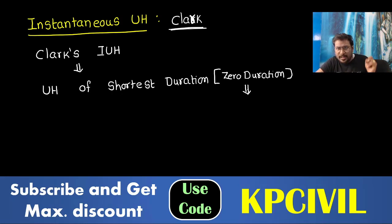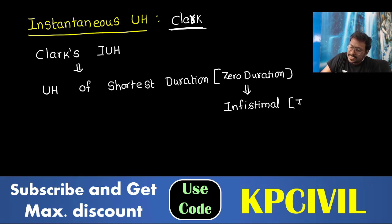I have taken only one value of discharge, starting at 0, ending at 0. What is the time gap? Exactly this instant, so that zero duration is called infinitesimal, or instant of time. A unit hydrograph plotted at an instant of time, infinitesimal, is the unit hydrograph of shortest duration, the instantaneous unit hydrograph.